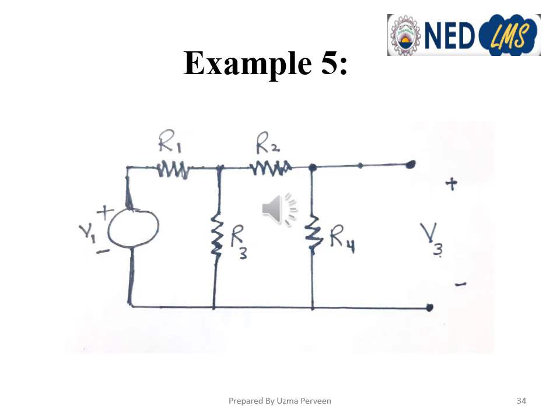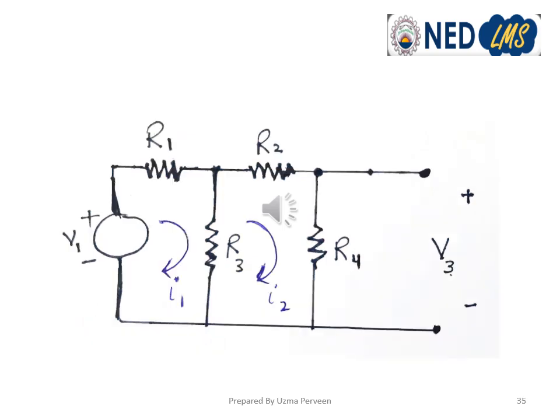So we'll see how many output variables are possible in this circuit, then we'll have that many equations. For example, if we have 4 possible outputs, then we'll have 4 equations. So first we'll decide about the number of variables, which helps us find the number of nodes, and we'll write equations, then we'll connect these equations in the signal flow graph, and then we'll apply Mason's formula to find the transfer function.